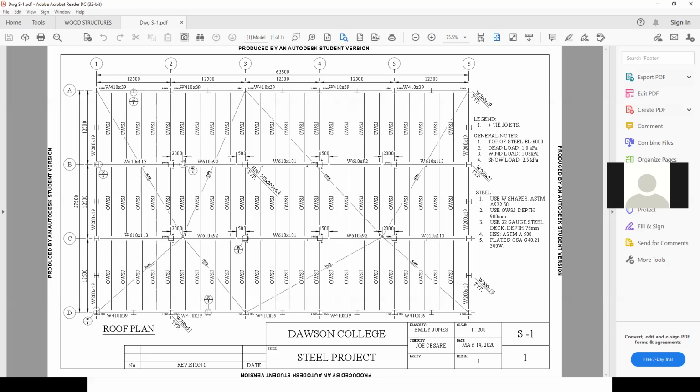So that means that by doing that, when they put all these different heights for all the columns for the steel, you're going to get all the right slopes in your steel structure, so that when they put the steel deck, you'll actually see the steel deck sloping towards your drain.